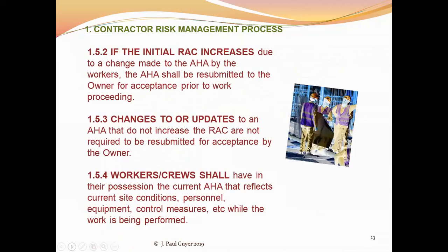Now, another point, and I mentioned this early on, is that this activity hazard analysis form, piece of paper, is a living document. As the work progresses, typically the construction supervisor may say, oh geez, we didn't recognize at the beginning that there was this additional risk associated with this task, and so I need to modify this activity hazard analysis piece of paper.